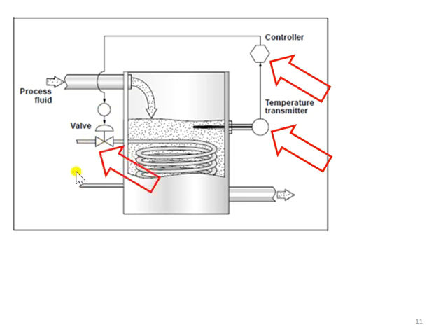But the problem will occur if the steam flow rate through the pipe here is not well regulated. So the controller will try hard to regulate the temperature inside this tank, but it will also be very dependent on the steam flow rate through this control valve.